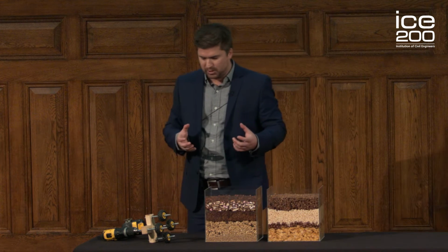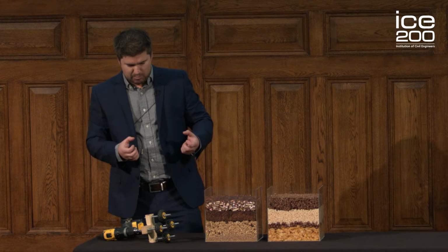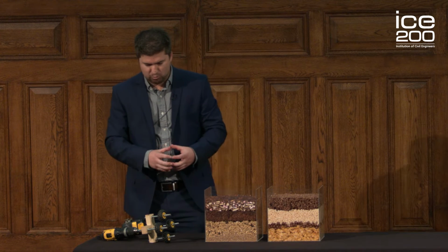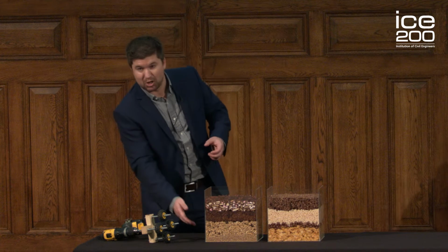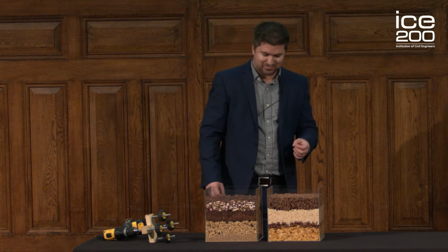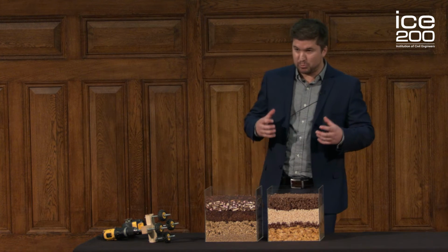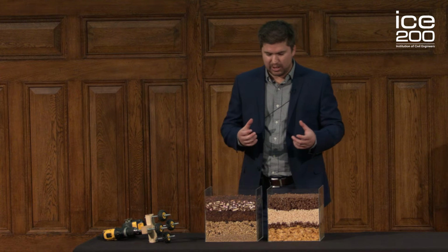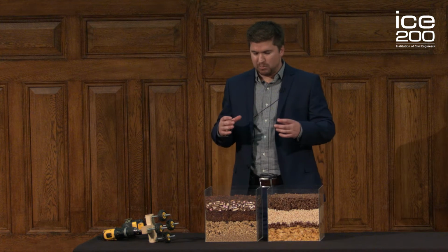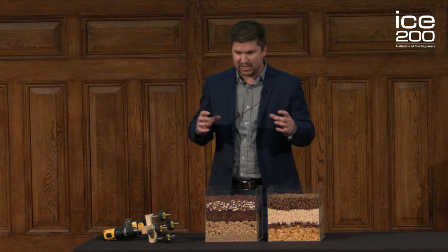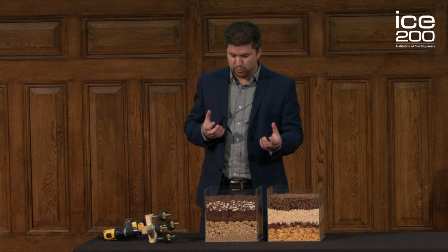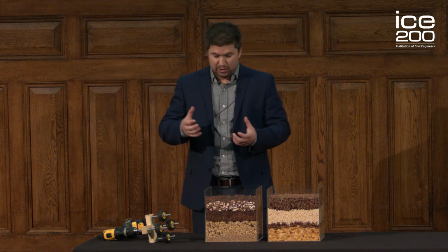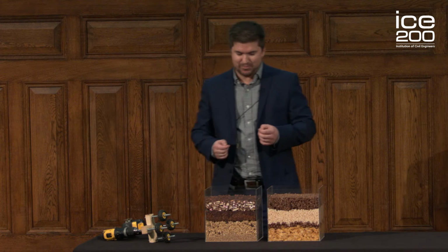So what we're looking for is something with a bit more meat to it, a bit more robust, so a range of soil particle sizes and free draining properties, like the grape nuts on the right-hand side. The next layer, to improve the strength of that subsoil, we put a layer of capping in. So what we're looking for is a dense layer with lots of different sized pieces of crushed stone and aggregates. So something like the granola on the right-hand side.